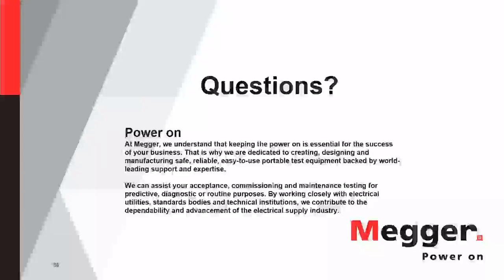And we calculate the difference between phases for you, but you can also look at the 3 times yourself. The problem is this breaker's moving so fast, so it might only be a millisecond of difference, and we allow a couple milliseconds to change there. Usually like 2 in the open, and I forget what IEEE says, it's like 4 or something on the close.